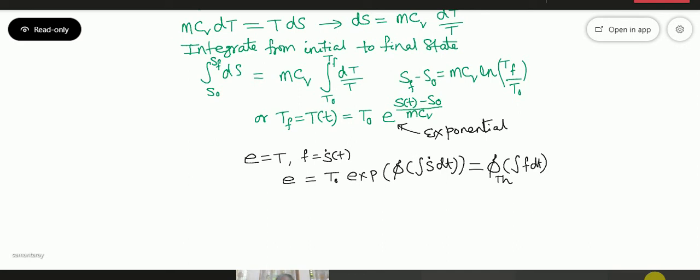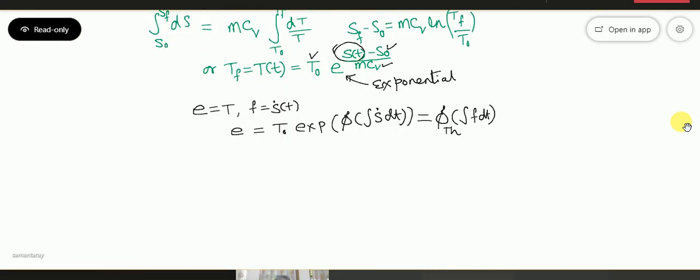So here you see this S, this is constant, this is constant, this is constant. This S comes from integrating the flow, and it has entered into the equation in a very nonlinear way. So we find effort is related to flow, but in a nonlinear way. So this again is a nonlinear spring. This is an energy storage in a pretty nonlinear way.